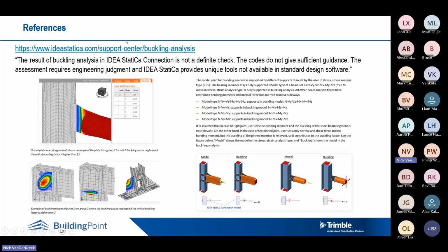And so from this article, we'll see the various situations I've described in the previous summary discussed. If we have a gusset connected member, and this will be the typical case with full restraint of the strut in the buckling analysis in the software, we need to have at least 15 as a buckling load factor, but otherwise a minimum buckling load factor of 3. So these are earlier articles and so on.